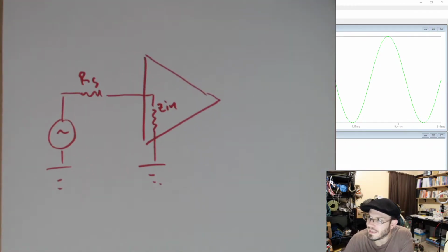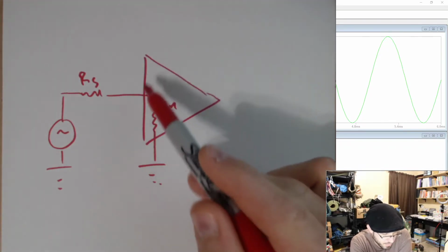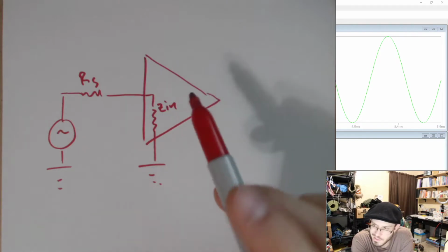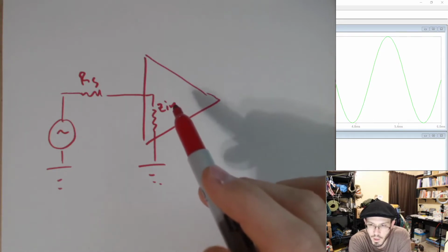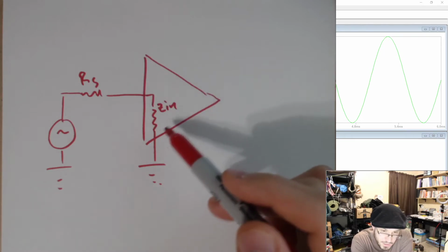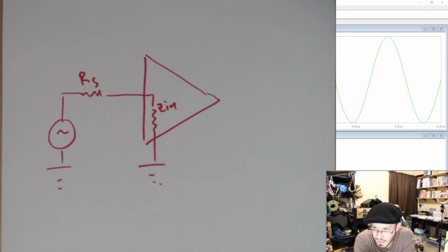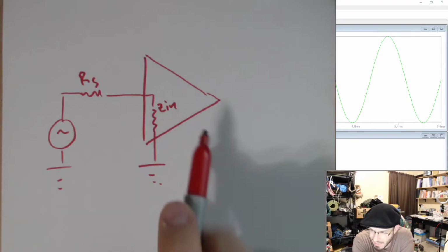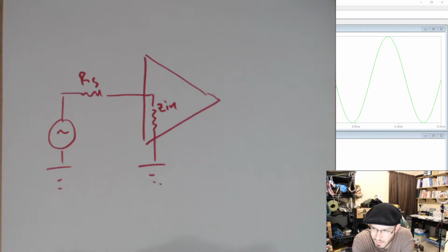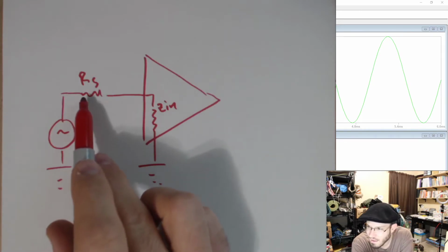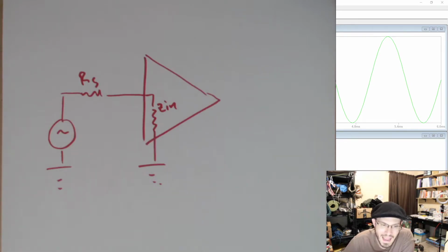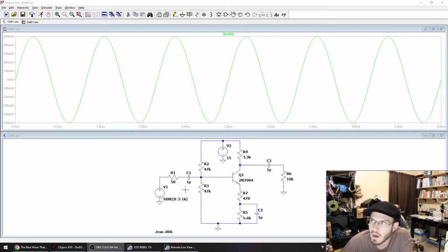So when you're calculating that amplifier parameter, you're calculating it for the whole common emitter. And this generic amplifier model is just a substitute. It's a stand-in for our circuit, and it's actually a stand-in for everything, including that capacitor all the way to the voltage divider bias, including the transistor, including all of that circuitry. So the RS is that 50 ohm R1 that I have in my circuit. So if I switch back over here, this is RS right here.